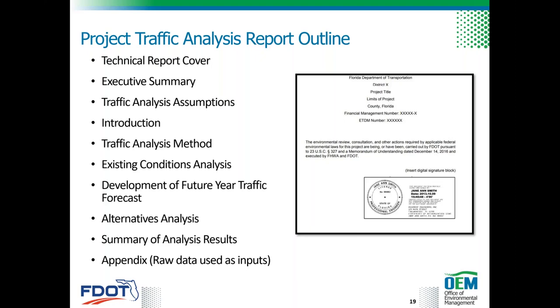Then the existing conditions analysis, and this summarizes the balanced turning movement counts for the study intersections or interchanges under existing conditions, and also summarizes operational and safety analysis for the existing conditions, including development and calibration of microsimulation models as applicable. Then also the development of future year traffic forecasting.